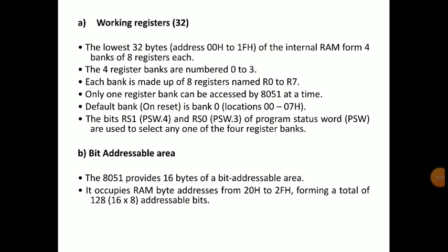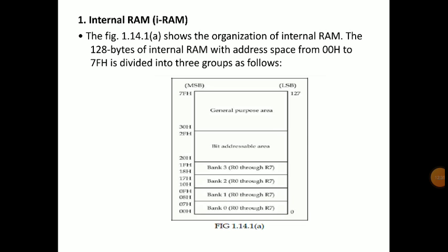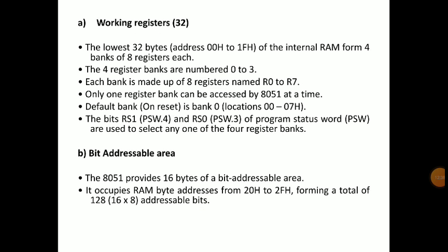Next portion is the bit addressable area. The 8051 provides 16 bytes of bit addressable area. That means from 20 to 2FH.